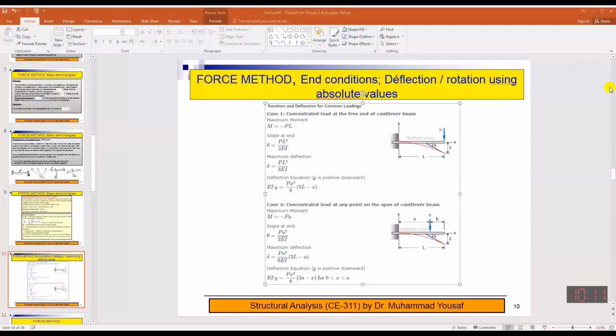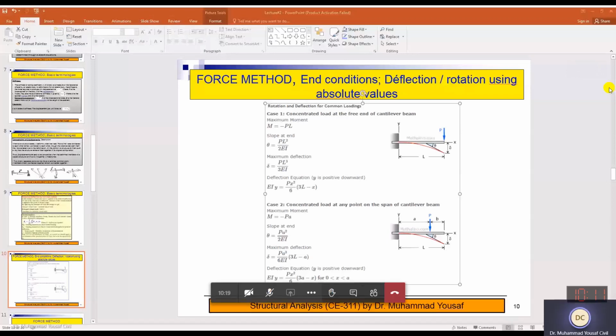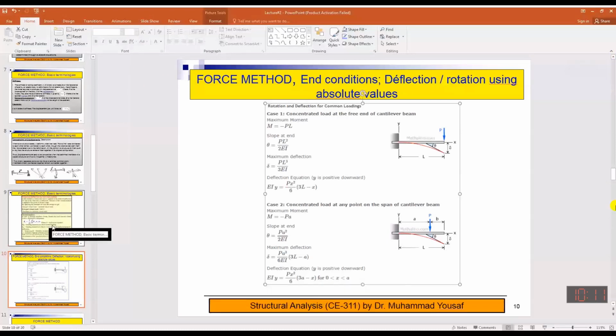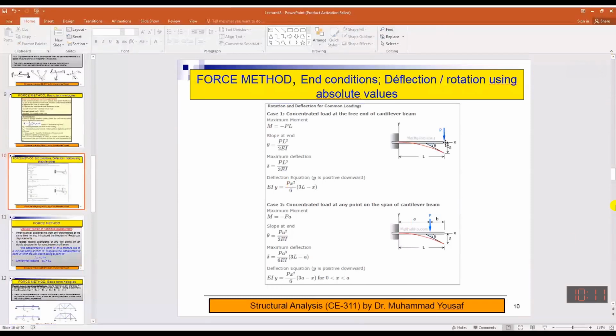So I was talking about the mode or the method for the solution of the numerical. Either you can directly put the value if there is a cantilever beam and the load is at the tip of this beam, and you are interested in finding out this delta and theta, then directly these formulas can be used.